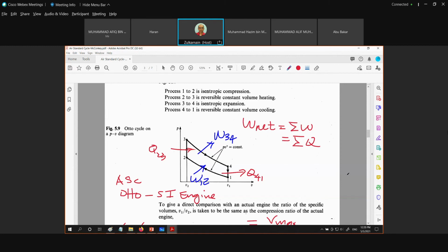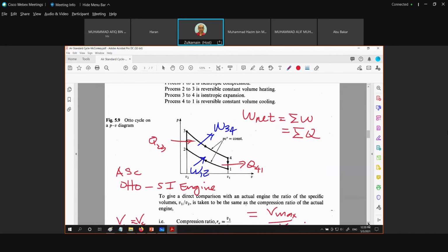But before that, when we drive the car or run the engine, we are going to have a certain value less than the maximum. So we have to admit that this is what we get from a heat engine. We cannot convert all the heat supplied, 100%, into W net in order to run the cycle. Okay? Any questions, guys?